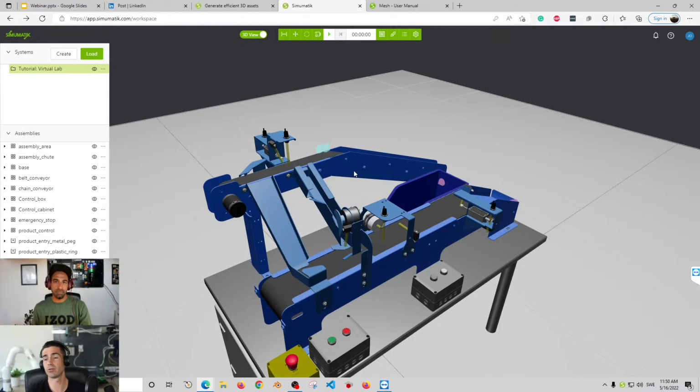And Rajbir, that OPC UA is opening a lot of doors. I mean, most of the PLC and robot manufacturers have integrated OPC UA. And we can do OPC UA. So basically, you can connect to anything compatible with OPC UA. This would be the best recommendation that we can use, because many hardware and software has OPC UA communication. And it's a time question. I mean, all the last generation CPUs in the market are almost coming with OPC UA.